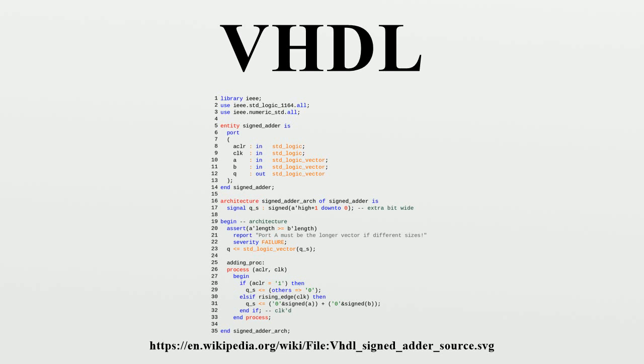A simple AND gate in VHDL would look something like: import std_logic from the IEEE library: library IEEE; use IEEE.std_logic_1164.all. This is the entity: entity ANDGATE is port, end entity ANDGATE. This is the architecture: architecture RTL of ANDGATE is begin O <= I1 and I2; end architecture RTL.